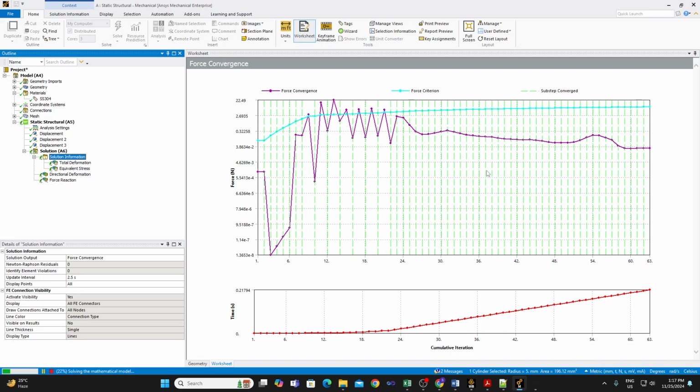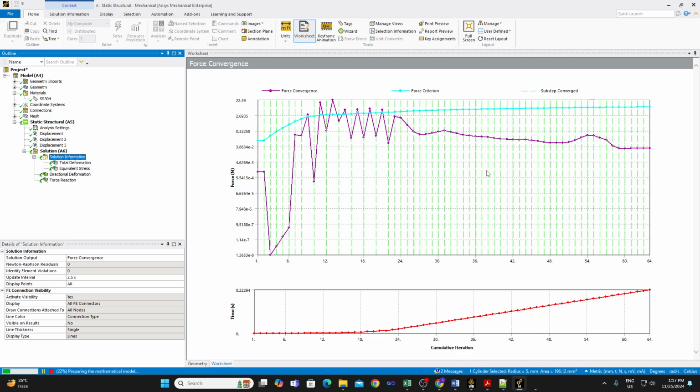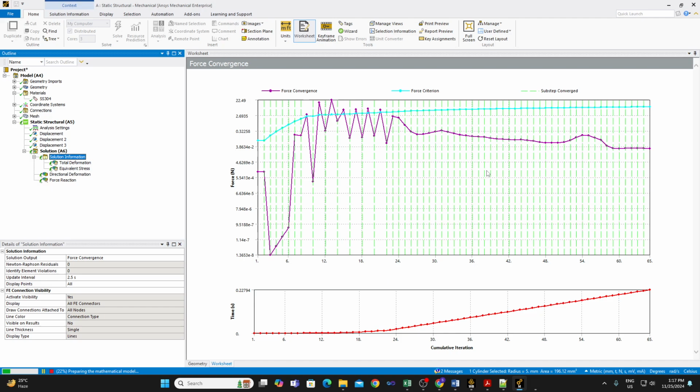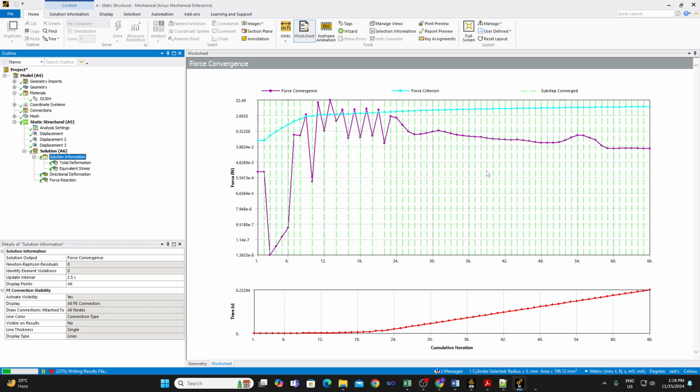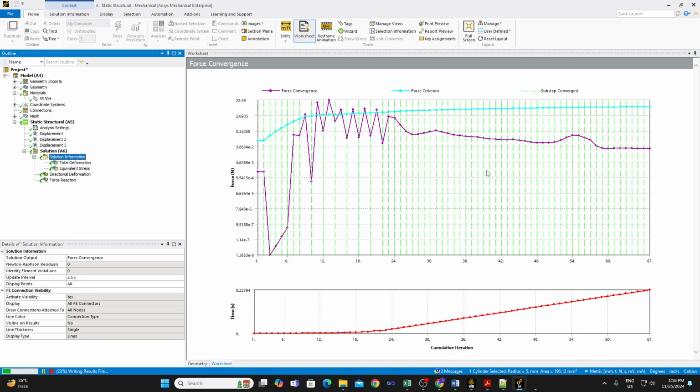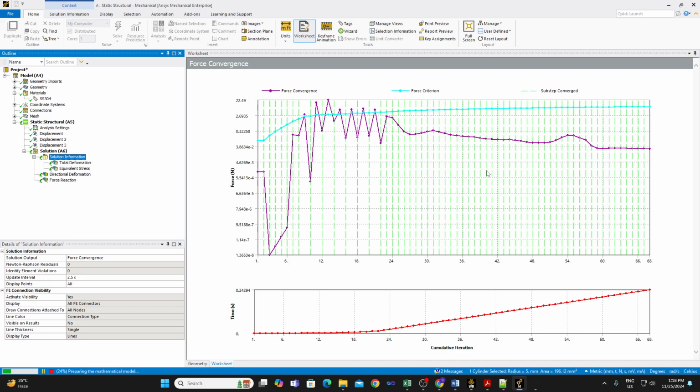Now remember, at the beginning of this video, I mentioned that the Chaboche plasticity model is a rate independent plasticity model. Keep that in mind. This is not rate dependent. Okay, but the material that we are using has dynamic strain aging, which is manifested typically at the smaller strain rates. So it has a rate dependent behavior. Okay, so our challenge is to see whether we can model the material behavior exactly with this rate independent plasticity model. So I'll let this convergence happen. It will probably take a while.